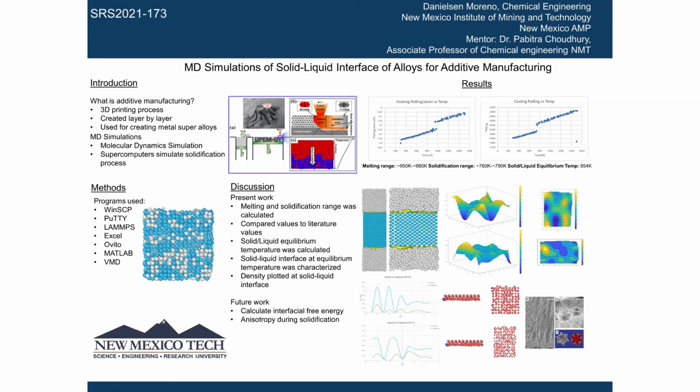And doing research, we found some papers that essentially explained that depending on the density at the solid liquid interface of the two components, you could have dendritic structure growth, which a dendritic structure is kind of like a crystalline, branched out structure, kind of like a snowflake, where essentially it doesn't grow just in one direction. It can grow in several directions as it solidifies.